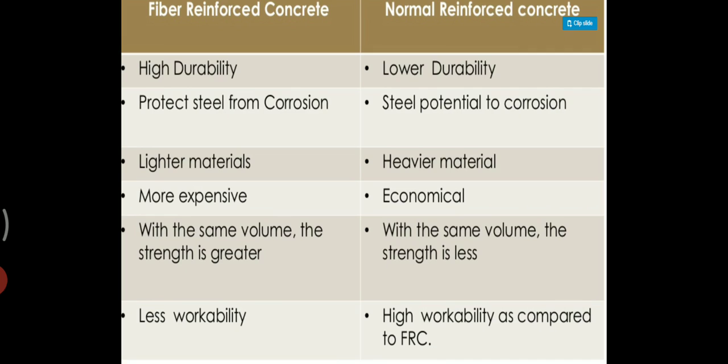With the same volume, the strength is greater in case of fiber reinforced concrete, but with the same volume the strength is less in case of normal reinforced concrete. Here the less workability is enough, but here high workability as compared to FRC. We need high workability to work.